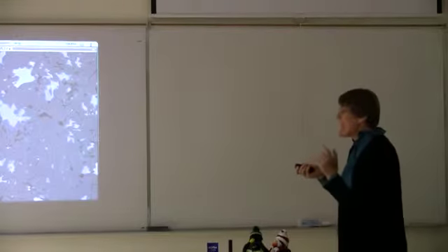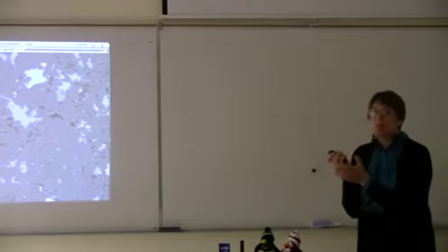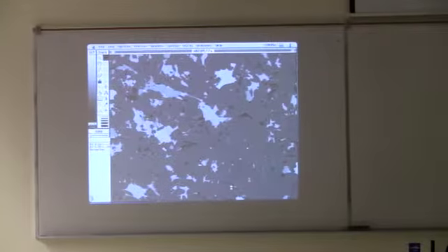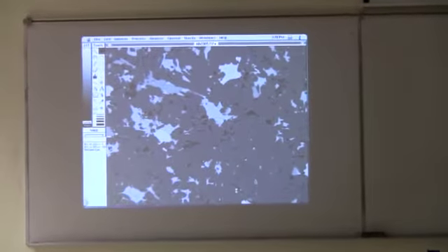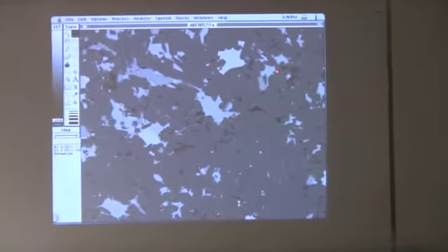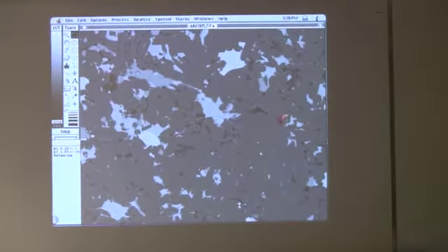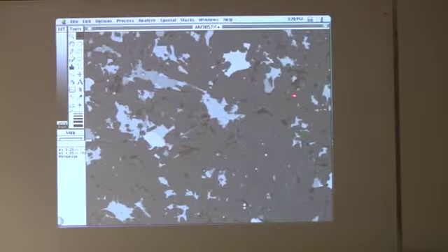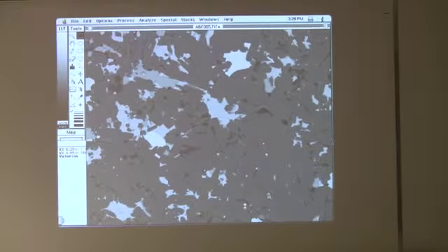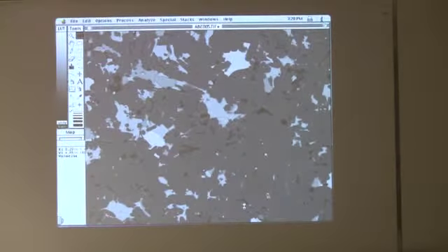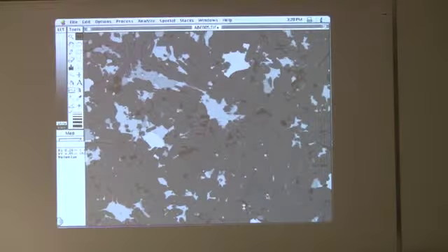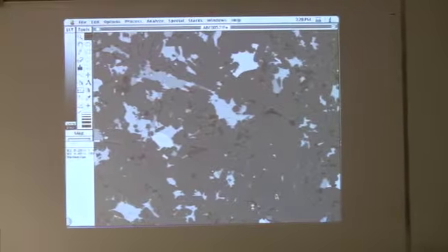But a slight sidetrack beforehand: how do we measure porosity in a thin section image? You take a backscatter electron image where you have high contrast between the metal grains. You can actually do some modal analysis this way too. I've done some of that. But the porosity tends to be these dark spaces, either filled with epoxy or completely empty. So it tends to be the dark pixel range down here on the range. So I measure the whole image. I can calibrate it, I don't need to, so I can just count pixels.